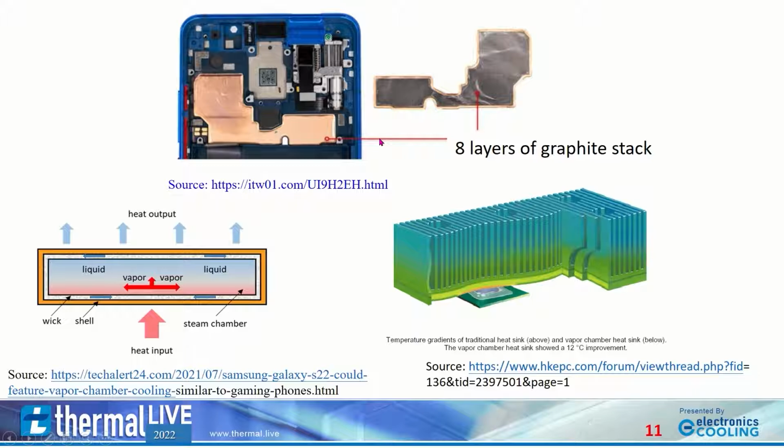However, when a two-way exposed thermal conductor such as the heat pipe or vapor chamber, or brittle materials such as graphite sheet or graphene sheet, is applied as a thermal diffusion device, in this case the K value of the heat dissipation device cannot be obtained by using simple Fourier's law. Why can we not use Fourier's law to measure the thermal conductivity?